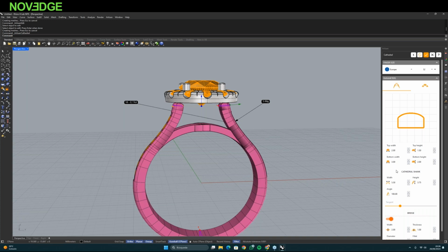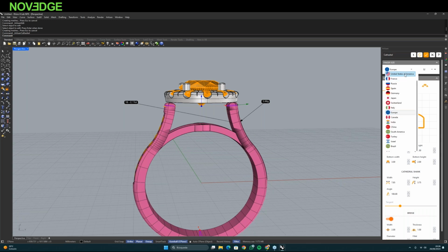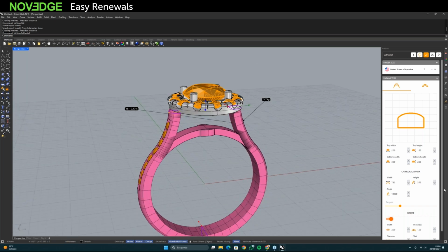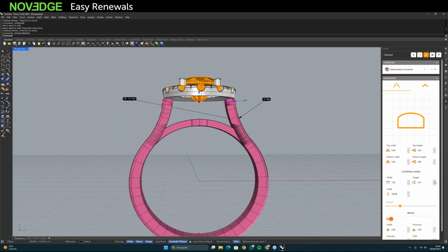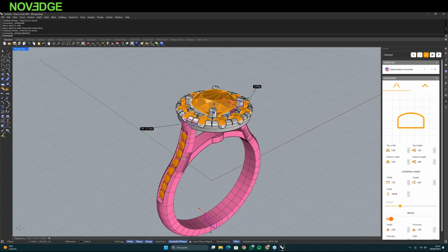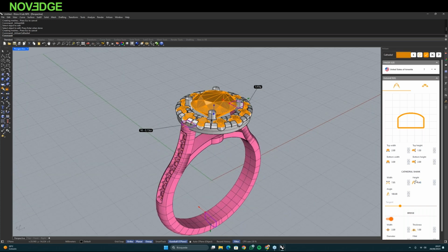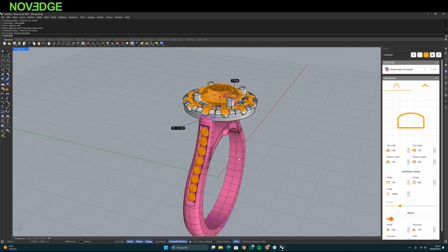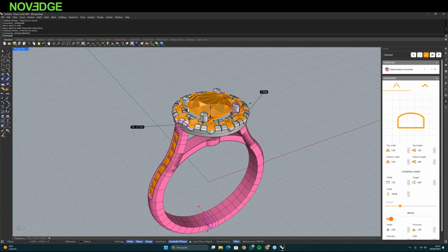The bottom width is also okay, but I want to increase this opening area here. Let's put it at 7, for instance, 7.5, or 8. Okay, I'm also going to adjust the size. And I'm going to increase the height here to touch the halo, and then reduce a little bit. So it's not visible here on the top. It intersects perfectly, so it supports the halo.